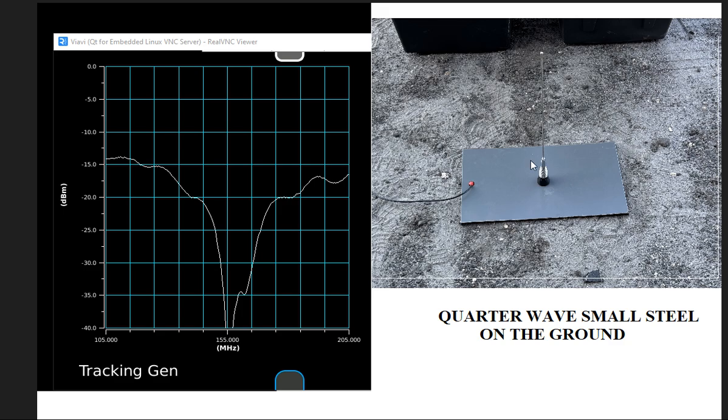Okay, guys, that's it for the antenna placement. And just like I said, keep that in mind whenever you're putting an antenna in an odd spot. You've probably changed something about it. More than likely, it's going to be its resonant center frequency. So you'll have to cut and tune as needed.